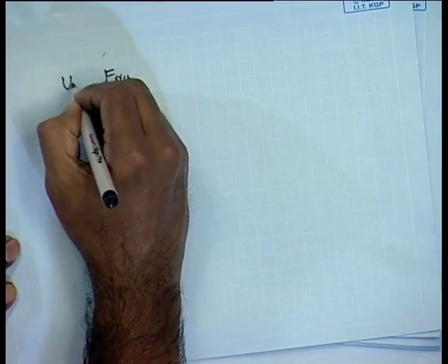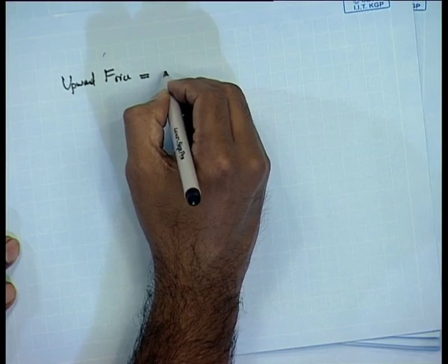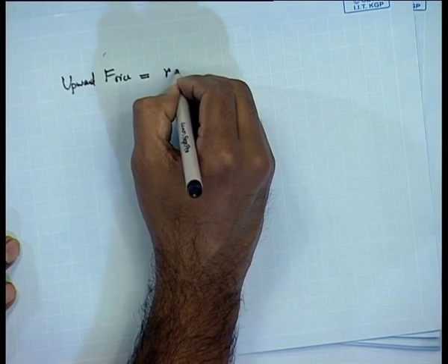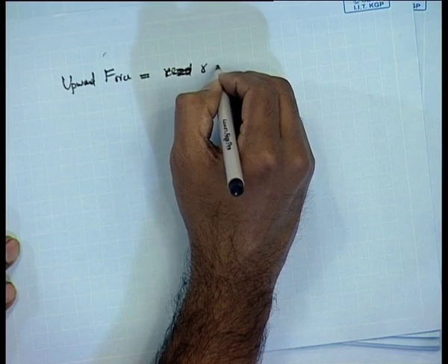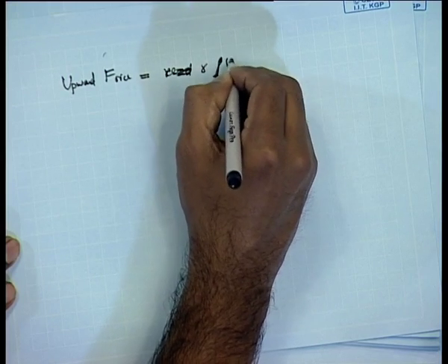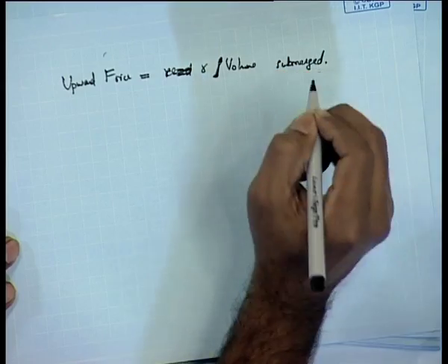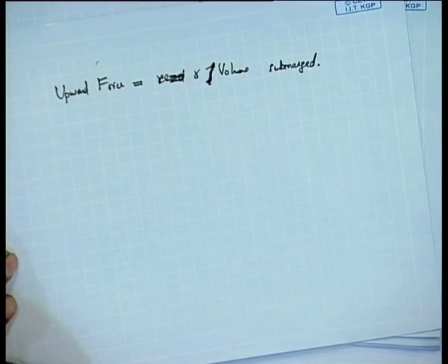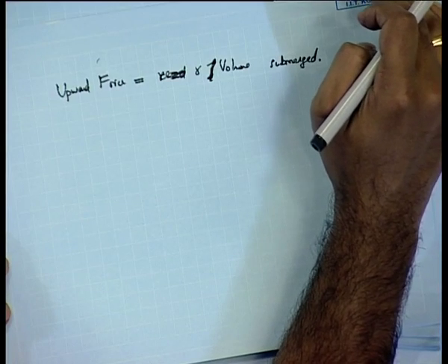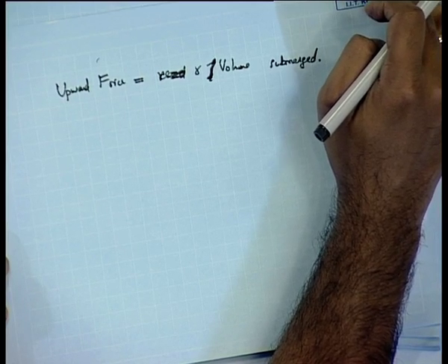the upward force or the vertical force, is equal to gamma into the integral of gamma into volume submerged, that double integral over s, and that was giving you the volume. So, it is equal to the volume submerged. This gives you the upward force on the body, and similarly, if you try to look at the horizontal component,